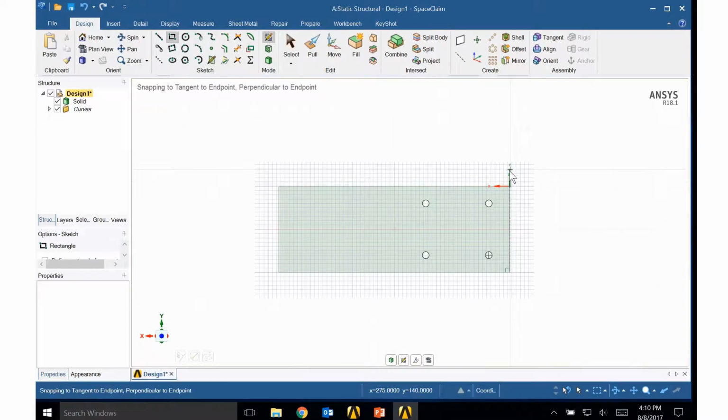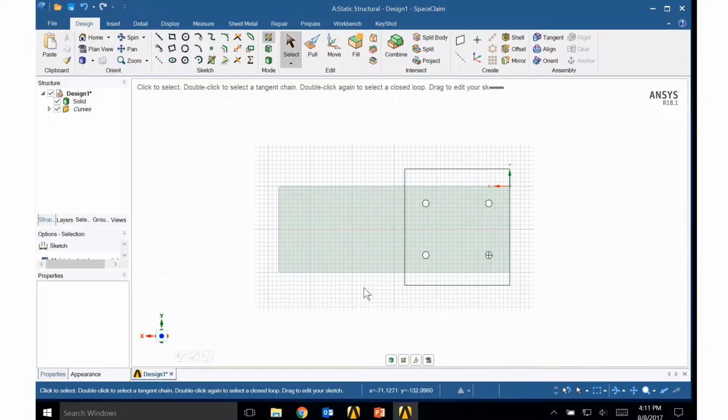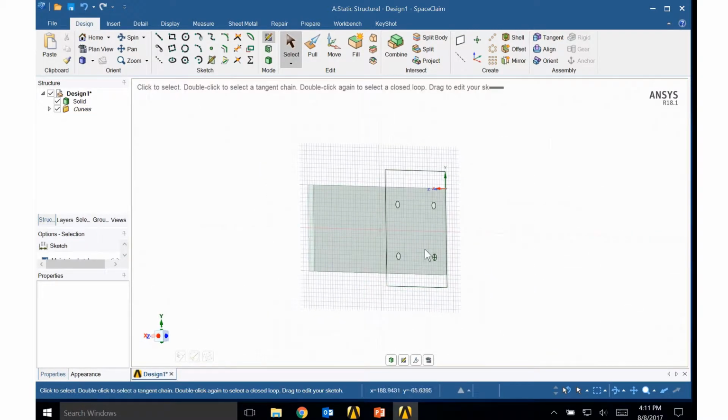in the vertical axis and drag it, and this will be a 250 millimeter tab, and maybe I'll make that 260, 270 to get a little more on the bottom, so I'll go 270, enter. And then on the top, that's going to be 250, 250, enter. Now I'm ready to go ahead and escape out of this and rotate it and pull this member out.